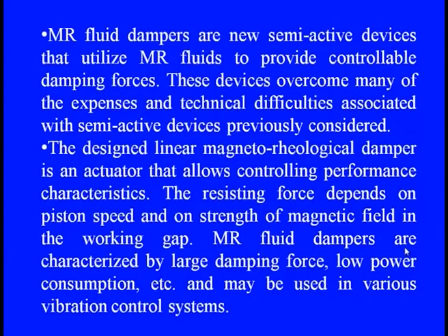The design of this linear magneto-rheological damper is nothing but an actuator which allows controlling performance characteristics, in which the resisting force depends on the piston speed and the strength of the applied magnetic field. Because in the working gap, the particles provide resistance according to their chain structure, but it depends on what the piston speed is and what the strength of the magnetic flux field is.